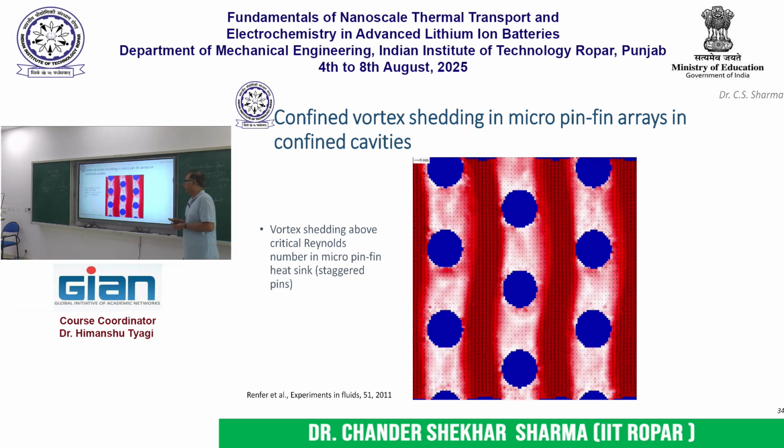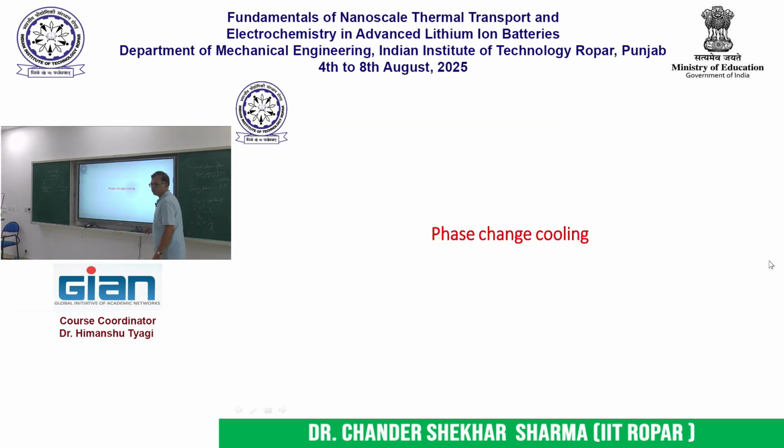Okay, so this was a brief overview of single phase cooling. Now coming to phase change cooling. If we let the fluid change its phase, then the fluid can absorb latent heat, and so we can deal with higher heat fluxes also.